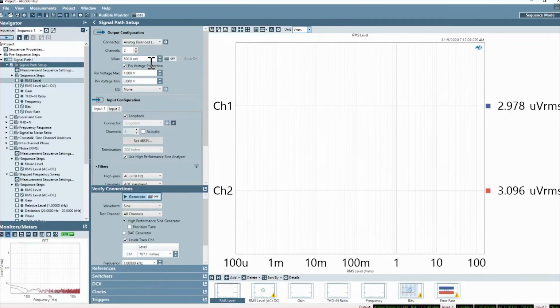When you have auto range enabled, all of that is, so to speak, hidden. That is to say, the analyzer itself knows when it changes the output range and coordinates that with the input side. So no measurements are made during the range transition period. And the timing of that actually does vary, but it's generally measured in milliseconds.